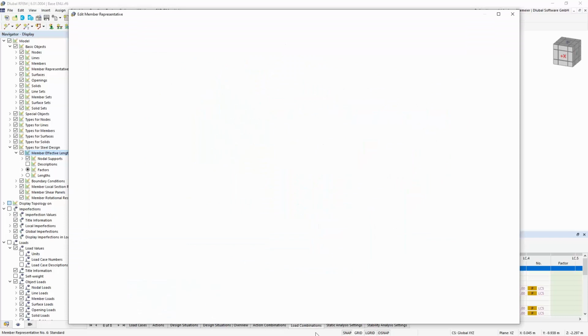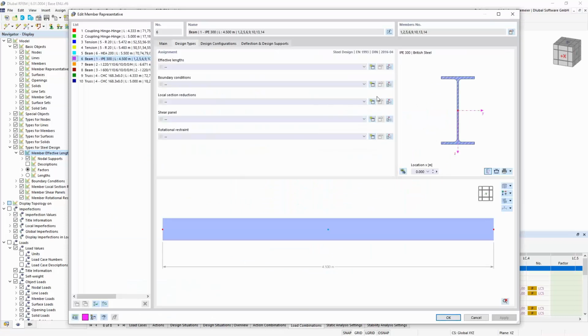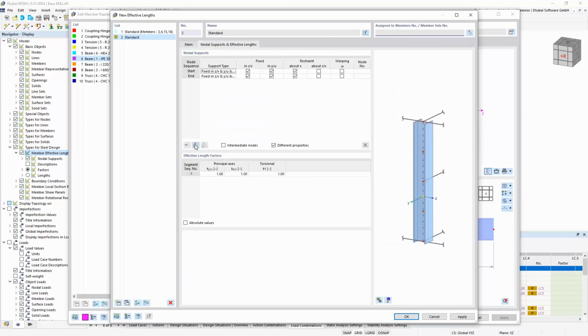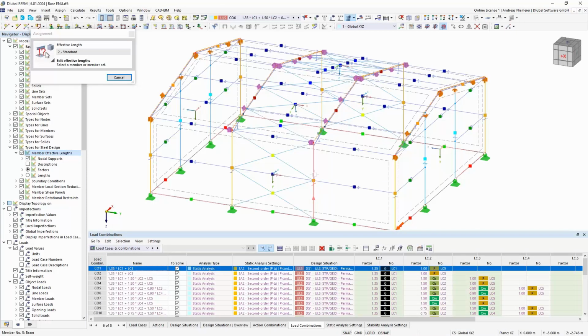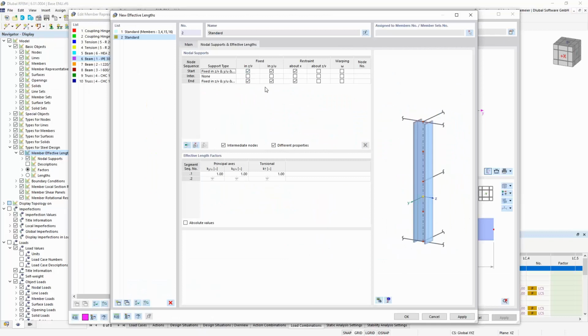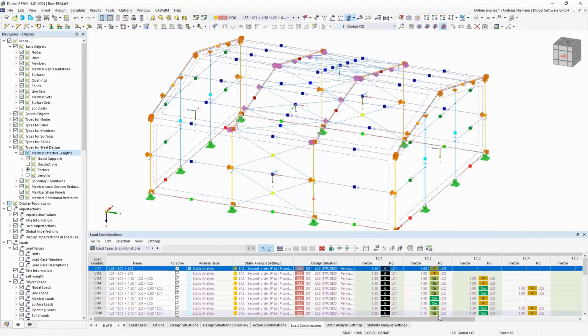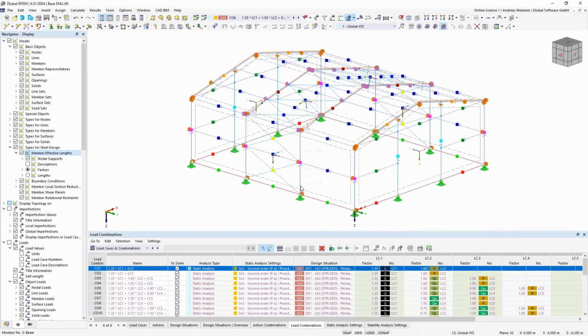So for example, this representative needs a buckling check for all directions, but all the columns will be braced in the middle for the weak axis, and for the strong axis we have a increase of buckling length with a factor 3.5, for example. Yeah, quite easy to distribute. So even now we have defined members, roof beams, gable beams.